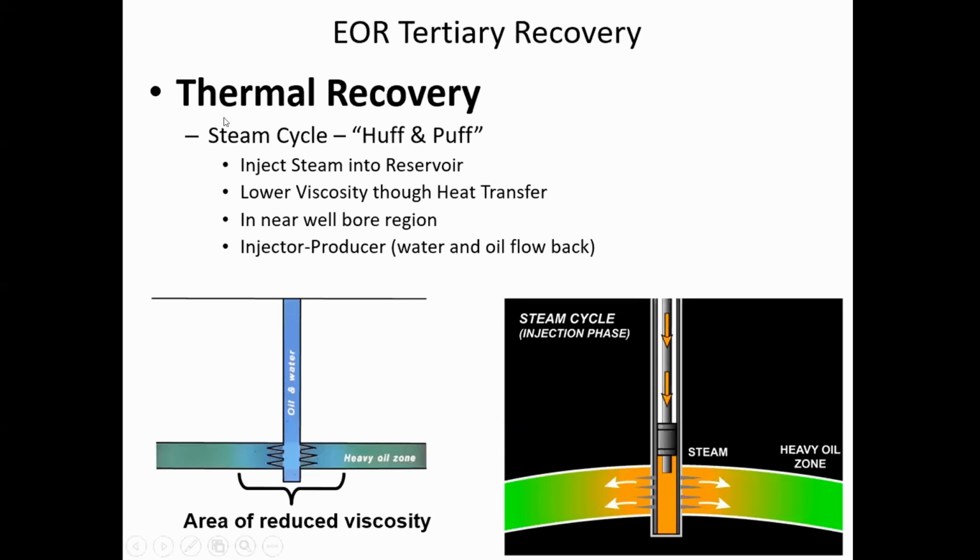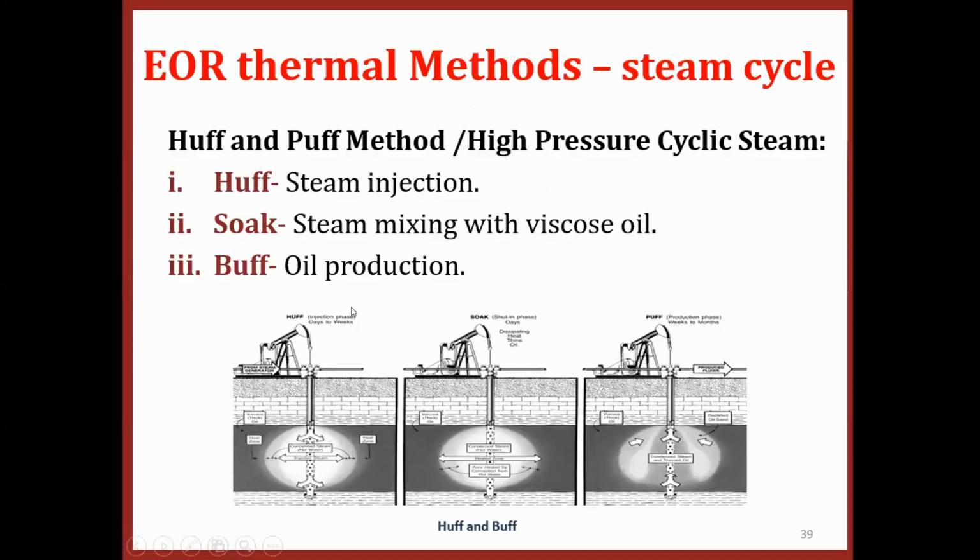This technique they call cyclic or huff and puff. So first in huff and puff, this is stage number 1. I prepare my steam and I inject it inside the reservoir. How many days? Maybe I keep injecting for 7 days, a full week. I start Saturday and I stop Saturday. When I stop, I shut the well, close it, and I go home.